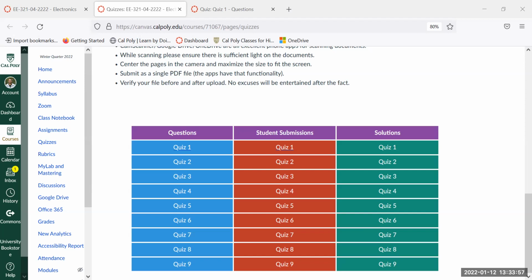If the anode is at higher potential than the cathode, it is forward bias, diode is on. If the cathode is at a higher potential than the anode, diode is reverse bias, diode is off. And those are the points we will use to actually analyze our circuits.